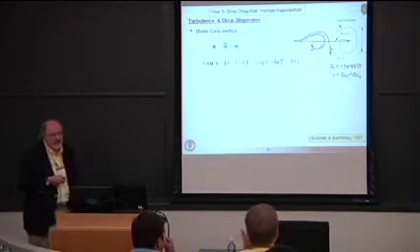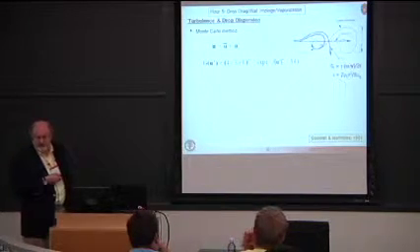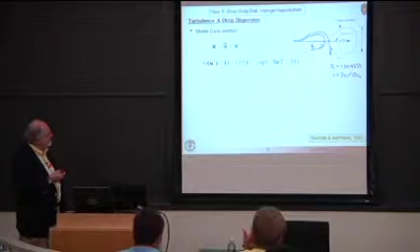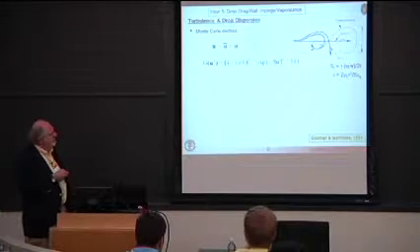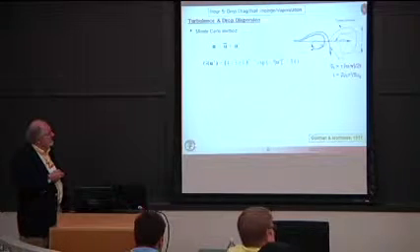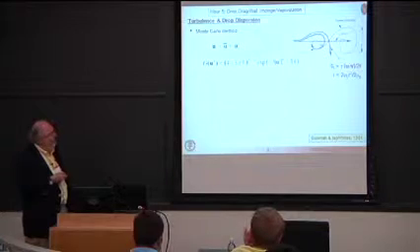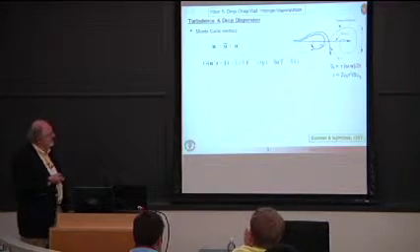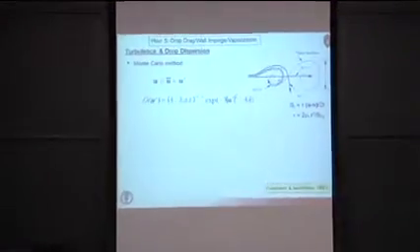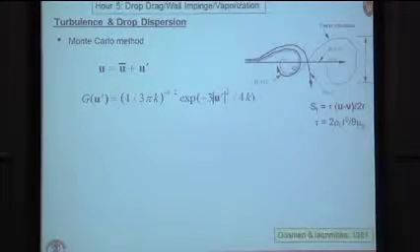Okay, so how do we characterize that turbulent flow? We have a mean flow, which comes from our RANS models, and then we have a fluctuating velocity. How do we pick this? Well, we know that the turbulent intensity is related to the kinetic energy of the turbulence. And Gosman and his group devised this strategy. They said, let's consider this to be a random process.